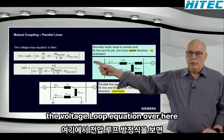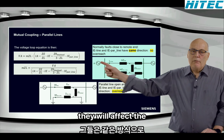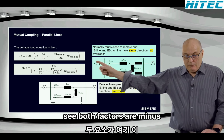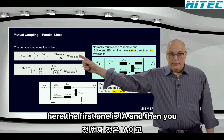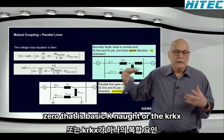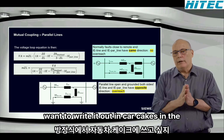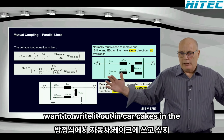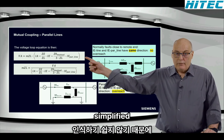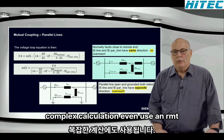Okay, so if we look at the voltage loop equation over here, they will affect the voltage in the same manner. And you can see both factors are minus. The three terms in this bracket over here, the first one is IA, and then you see minus IE times ZE/ZL, that is basically K0, or the KR, KX combined as one complex factor. I didn't want to write it out in KR, KX, because then the equation would become unmanageable and not easy to recognize. So this is a simplified way of showing that, and it is also used with a complex calculation, even using an RMT method.